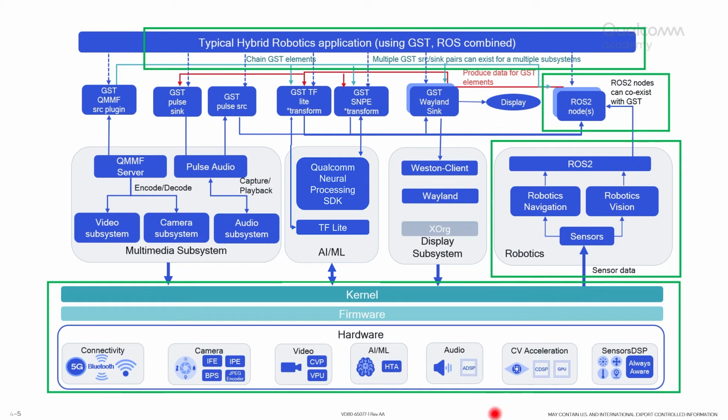At the bottom layer right here is basically all the hardware connections to the dev kit. These are sensors, IMU sensors that are already on the development kit, camera compute blocks that are getting camera data from the ISP and then making them available to the application using the IM SDK or the GStreamer plugins. The sensor data especially is also abstracted to the application layer using ROS. So the IMU sensors on the dev kit are available to developers using a ROS node, right? So we'll take a look at some steps of how you can actually get this data.